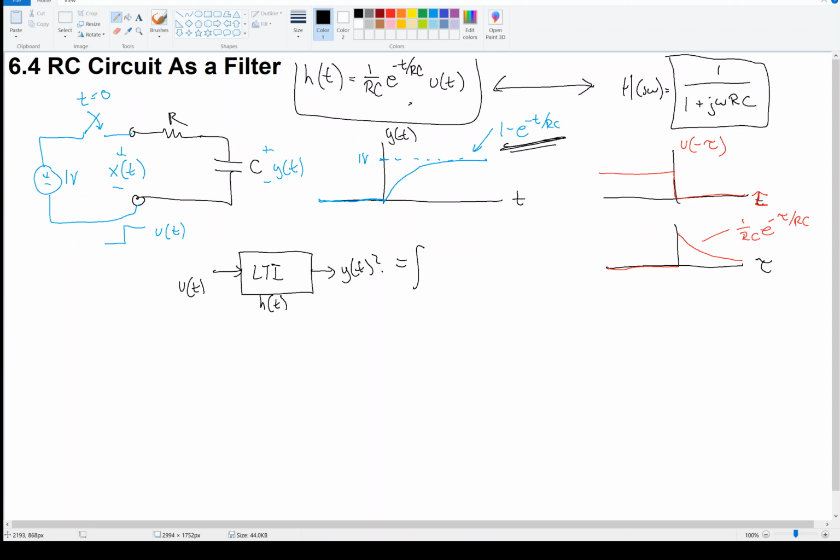Now, for the convolution, notice that y of t is equal to 0 for t less than 0. And that's because if I shift this graph, which I flipped already, to the left at all, there's no non-zero overlap. So shifting it to the left is t less than 0. No non-zero overlap means y of t is equal to 0.